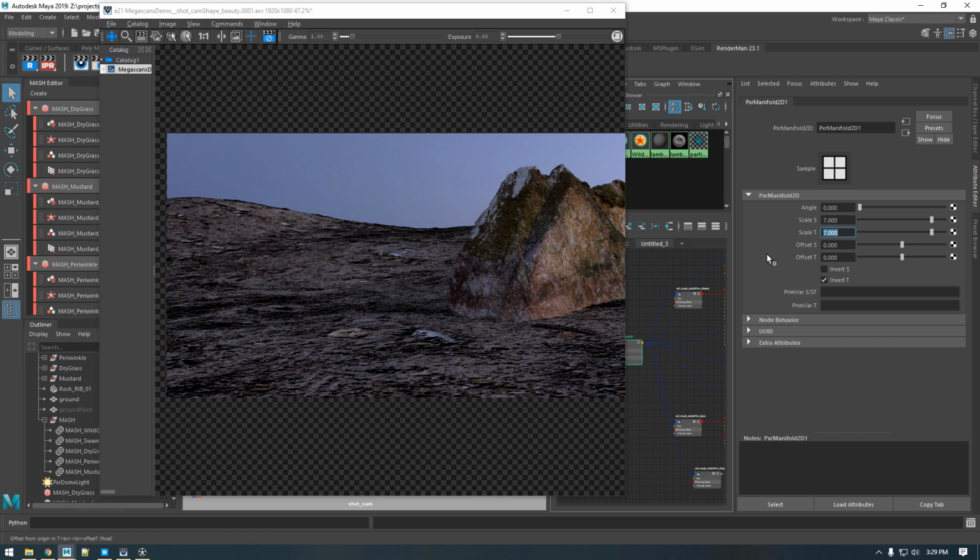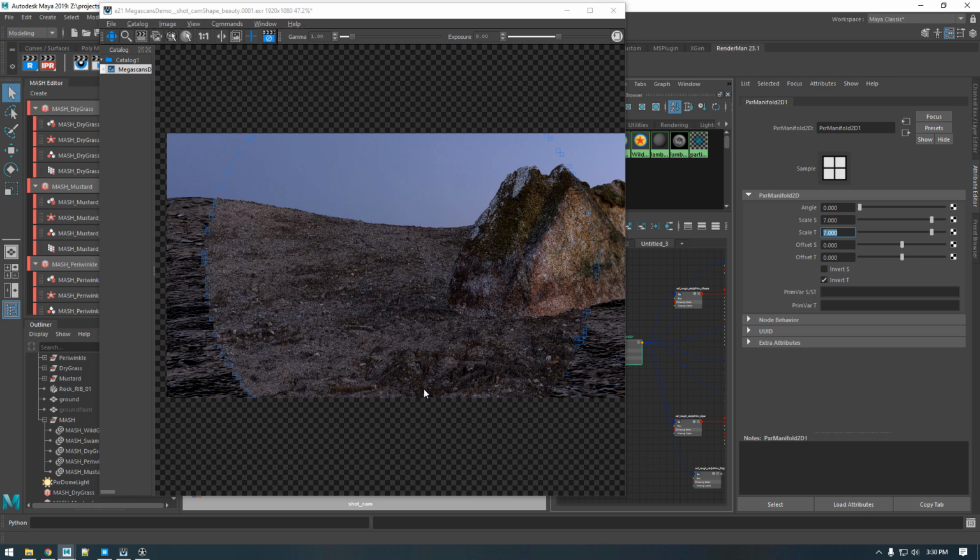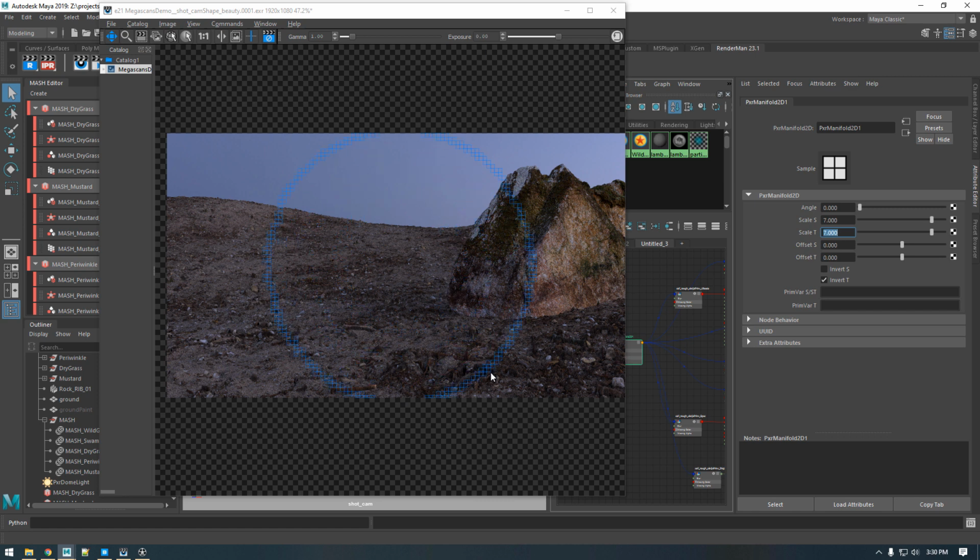And then after you change this, it's going to take a sec because it's got to rediced the geometry for displacement. So it's starting. We'll see. Again, it takes just a moment. Alright, so it's begun, and initial looks, I can tell the displacement is a little too high. Some of these things are jutting out a little too far. I think I like the repeat though.